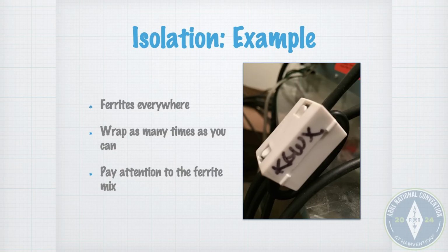But you do have to be careful about the ferrite mix, because they're not all the same. You want ones that are going to give you a reasonable response, because they're not completely linear devices. So you want to make sure that they're giving you enough inductance at the frequency of interest, because some of these ferrites don't have the same mu, which is how we measure this, at different frequencies. So you got to watch out for that.